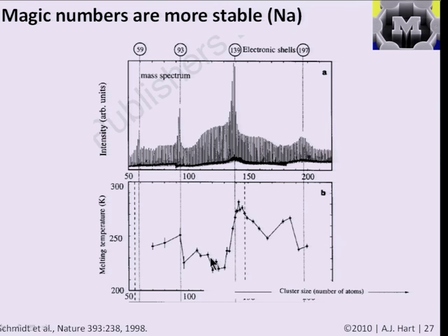But in practice, it's just important for us to see that the melting point decreases due to these surface effects, and that can have a profound effect on processing and synthesis. It can also, for example, mean that you can convert a bunch of nanoparticles into a solid at a much lower temperature than you would, say, melt that bulk solid. So there are implications for bulk materials processing as well.